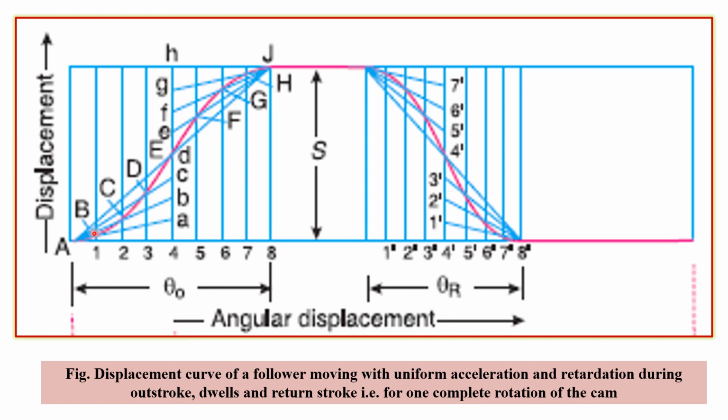Then we start joining this leftmost bottom corner of this rectangle, that is point A, with point small a, point A with B, A with C, A with D, and we look at the intercept made by the line A small a with the first ordinate.